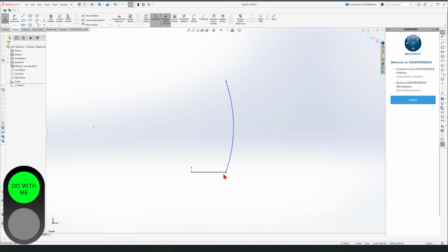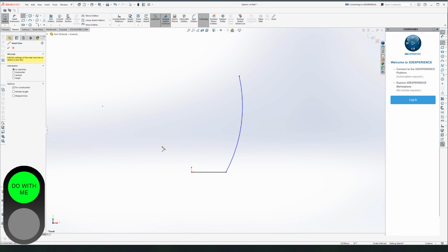I don't like the look of it. So it means this point and this point should not be vertically aligned. So I'm going to drag this one to the right somewhere here. Then we click on this arrow on the line to see the sub options, and we pick center line. We click on the origin and we go vertically up. See, it would snap here.